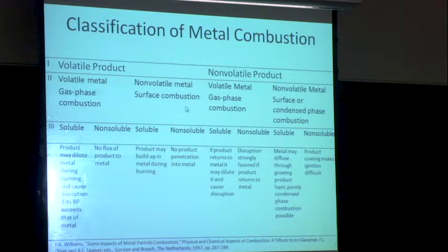So, again, recognize that all these metals that we're talking about in particle form and even in bulk form, they have an oxide layer on the surface, right? And that's what basically prevents a very, very small particle from being pyrophoric. Okay, so if I have something like bulk aluminum and I scratch it, I remove that oxide layer, but very quickly that oxide layer builds up again, and I dissipate all the heat from the reaction in the bulk material, so you don't see any temperature rise.